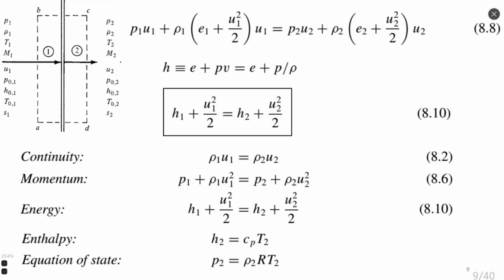and we obtain our classical form of the energy equation, which we saw last time, right? It is the balance of enthalpy on the left and on the right side of our control volume. And I will also put here that it is all equal to stagnation enthalpy, right? This enthalpy balance is constant for isentropic flow, and you will see that for non-isentropic flow as well sometimes.